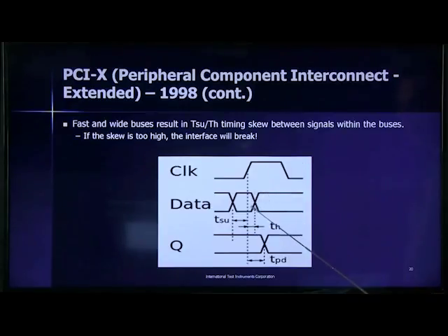Essentially, this is an electrical engineering issue with digital design, which says that if you have a digital signal that you clock in a flip-flop, you have to have the signal stable, outside of the invalid voltage zone, so it either has to be a clear high or a clear low a certain time, which is the setup time, from here to here before the clock signal comes around to latch the signal. And the same goes after the clock signal. The data signal has to be stable during this hold time.